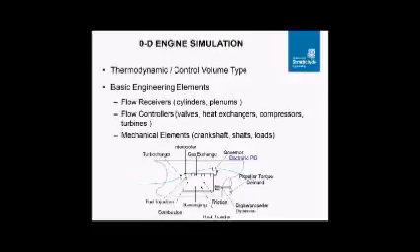Work, heat, and mass transfer take place across the boundaries of the control volumes. This is achieved by applying the conservation equations in appropriate form to each control volume. So, engines have several flow receiver elements, control volumes, interconnected by flow controller elements.